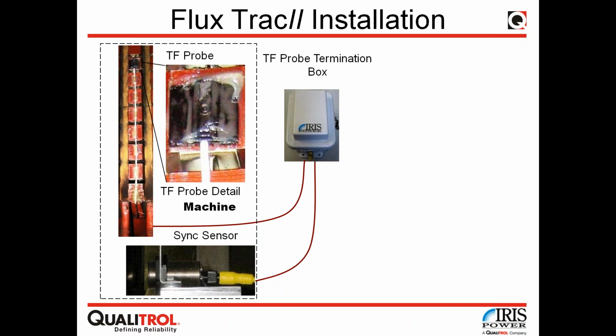Oh, we have one. It's a comment to the last question. A flux probe could only be installed online if the stator is not hydrogen cooled. That is true, but we are talking about motors today, and most of the motors are air cooled. Okay. But the comment is accurate if you are talking about generators.